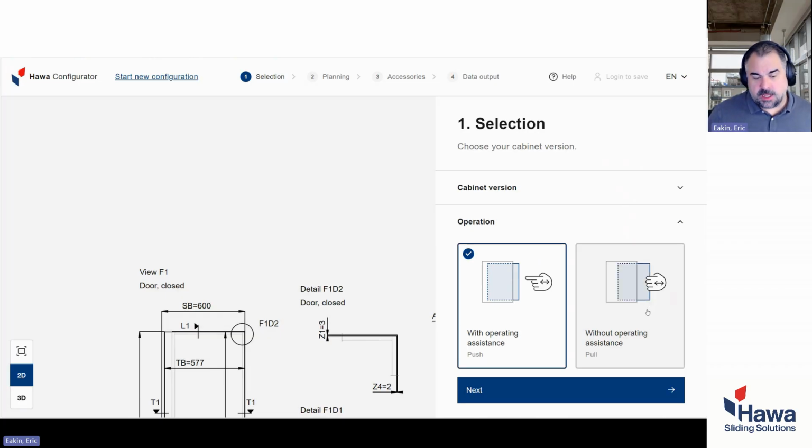On the opposite end of that, if you do need a handle or you're designing for a handle, we recommend that you use the pull version. And the reason for that is because the push hardware has an ejection clip on it, essentially in the back, that grabs onto the stop plate.